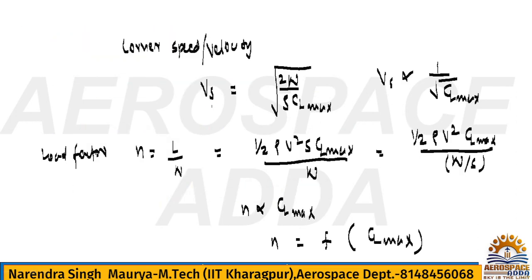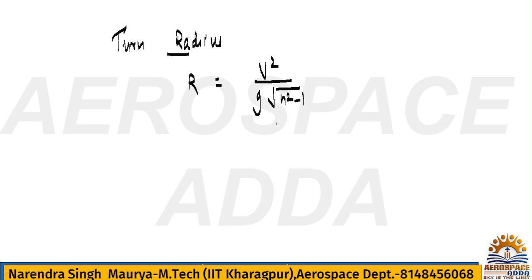Now coming to this, it is a function of CL max. N is directly proportional to CL max, so because the lift coefficient is maximum, this load factor will also be maximum.